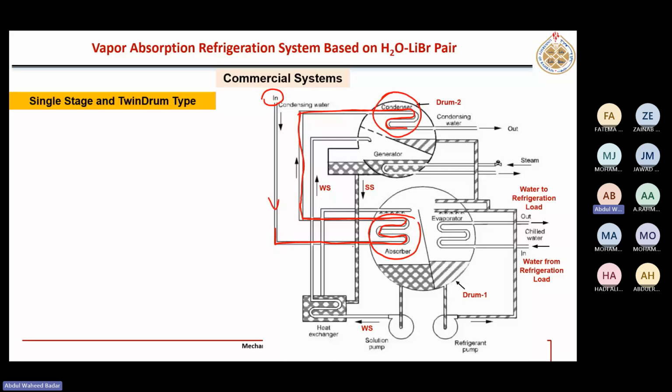So this cooling water first absorbs heat from this low temperature absorption system, and then it goes into the condenser where temperature is high, but still the temperature of this water is lower than the water being evaporated in the generator. And then it goes into the cooling tower again. So maybe I can show a cooling tower here. And in the cooling tower, you already know from chapter 4, there is air flowing, and this heat is transferred to the ambient air.